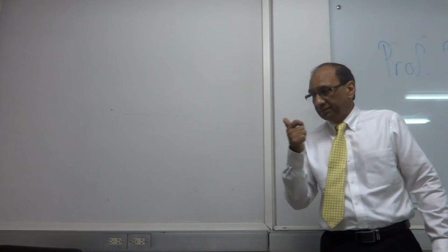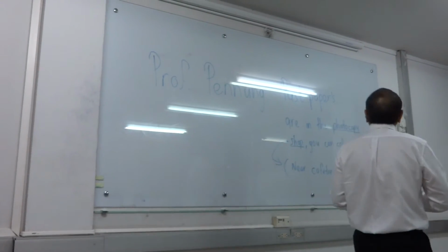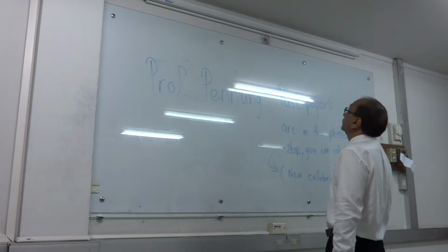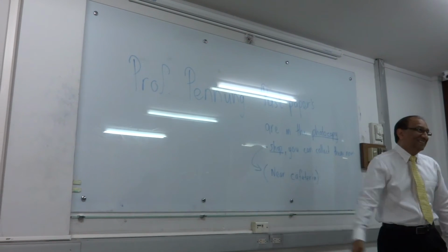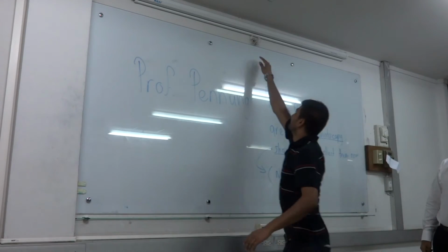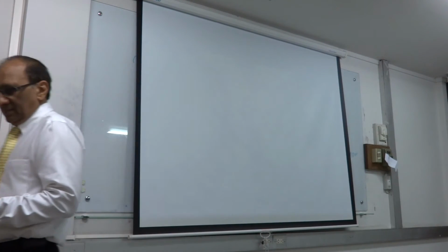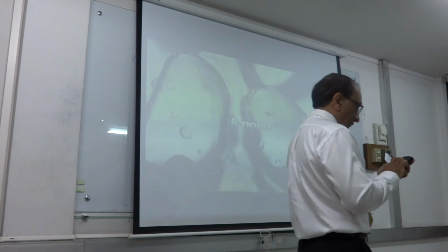So after we calculate the concrete capacity in torsion by using these equations, then let's say the torsion capacity of concrete comes out to be 10. What would be the units of torsion? This, by the way. What is the units of torsion? Sorry? Okay, Newton millimeter, whatever, but it's a moment, right? It's not shear. So that automatically tells us that it has something to do with the moment. It's a couple, right? Two forces together.